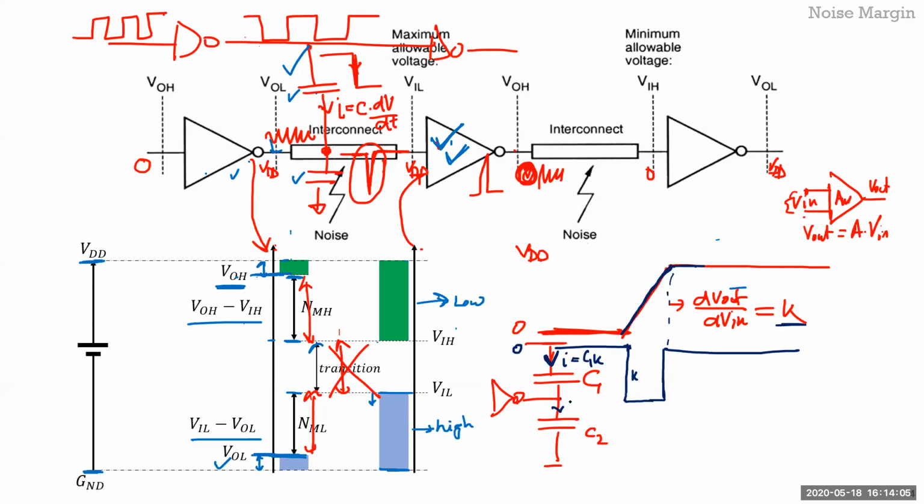Let's call this Vx. Vx is sitting at some value, VDD, and then it'll start decreasing, and then it'll ramp up. So that's the glitch. And that glitch happens only around this area. It remains quiet otherwise, and just happens during this area.